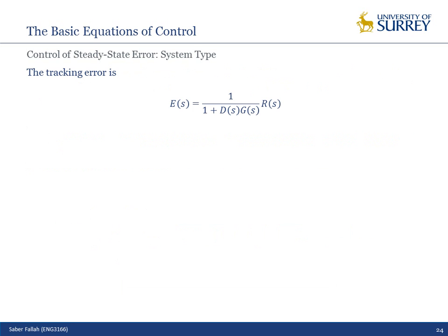So far, what we talked about was for a constant input, or a regulator. What is going to happen if we have a reference input which changes with time? To check the reference tracking of the closed loop system, we need to check it against some basic inputs: step, ramp, and parabola. I will check each of these inputs. First, let's start with the step input.